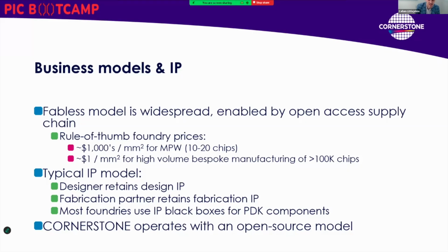If you're wondering what it costs, obviously it depends on the platform and the complexity. So, some very generic rule of thumb foundry prices. The entry level is what's called multi-project wafer. This is a cost sharing mechanism where you buy a small number of chips on a big wafer, but it's shared with other users. The typical cost of this might be in the thousands of dollars per millimeter square.